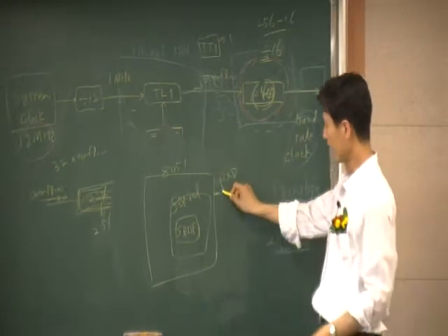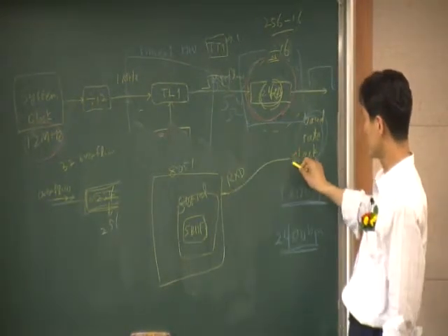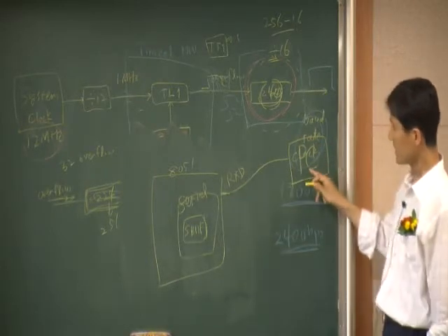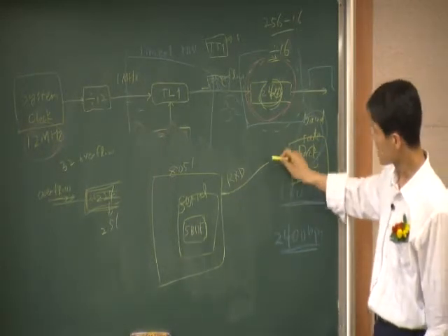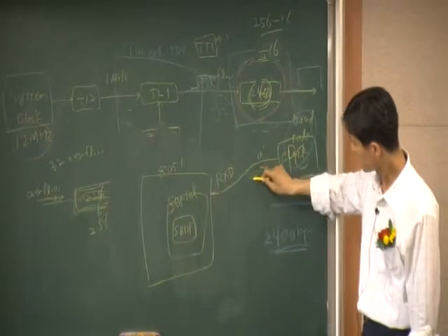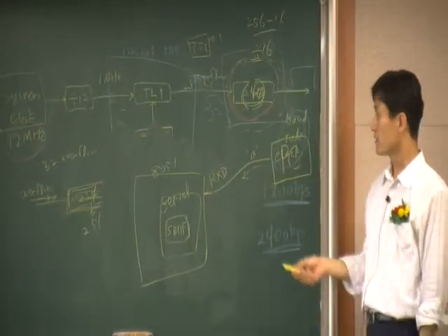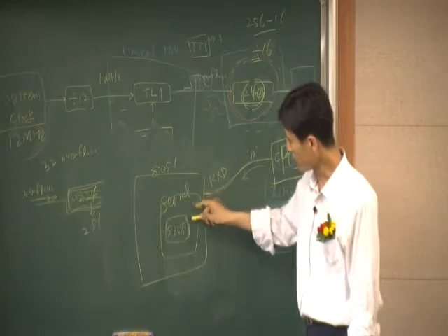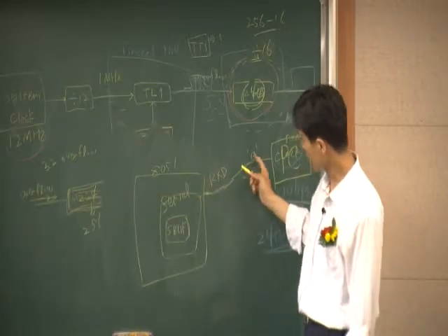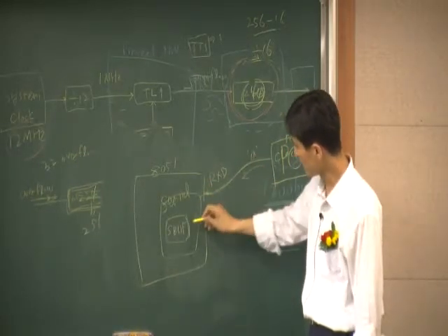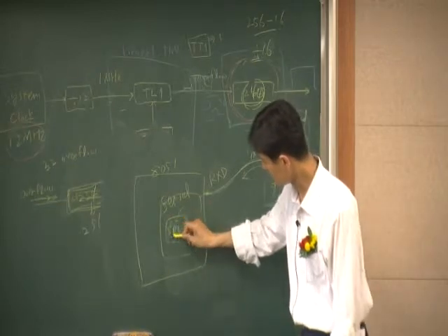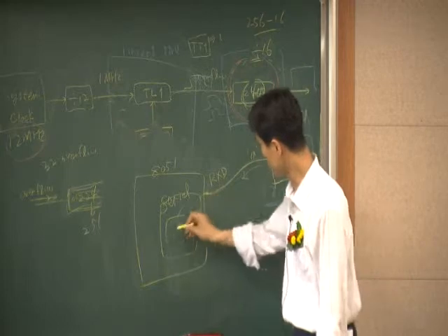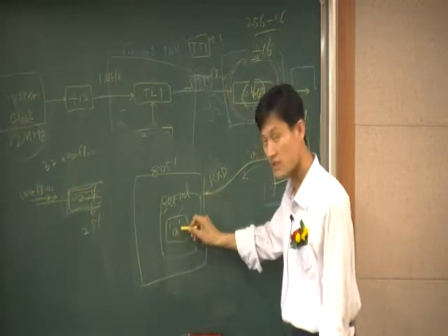It is connected with, let's say, a PC, and in the PC we are transmitting letter A. This letter A goes over here, and this hardware block basically receives it and copies this value into SBUF, like this, right?